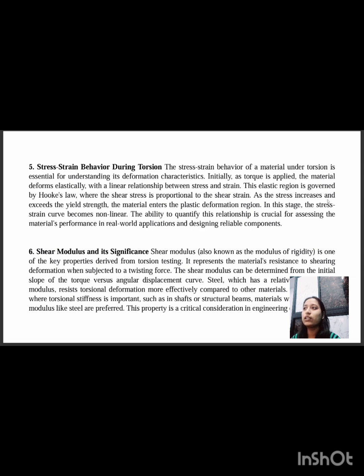The elastic region is governed by Hooke's law, where the shear stress is proportional to the strain. As the stress increases and exceeds the yield strength, the material enters the plastic deformation region. In this stage, the stress strain curve becomes non-linear. The ability to quantify this relationship is crucial for assessing the material's performance in real-world application and designing reliable components.